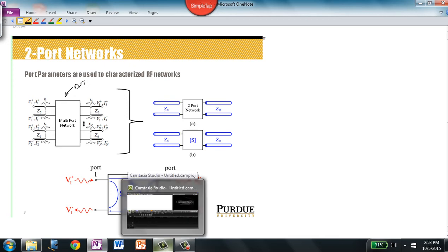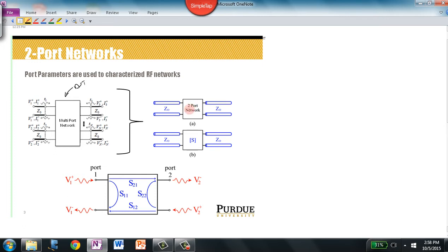The question may arise: why would we do this? The advantage of the two-port method, as we'll see, is that it more easily models device behavior that's nonlinear. It's really easy to analyze capacitors, inductors, resistors, and transmission lines. It's a lot more difficult to analyze, at RF frequencies in particular, transistors and such things.